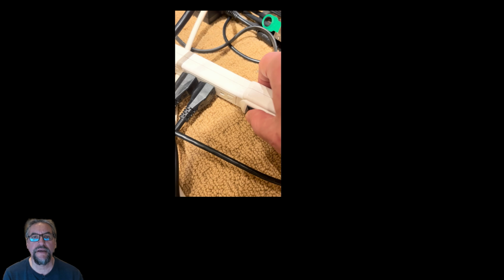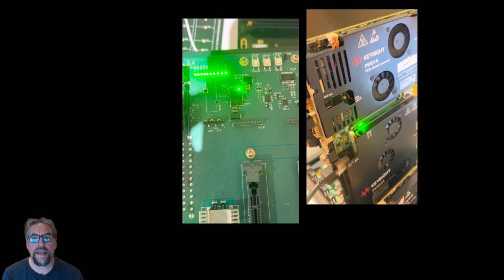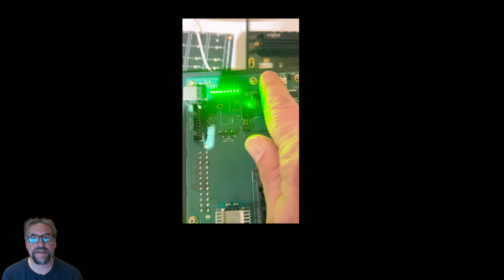When you're powering up, it's always good practice to power the backplane up first, then start up the power for the other devices. I like to have them on a power bar so that they all come up together, and wait about 20 seconds after powering the backplane before starting the other devices. Another good practice, once they're up, is to press the reset button at least once. That seems to get things going really nicely.